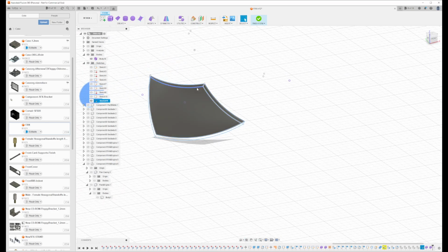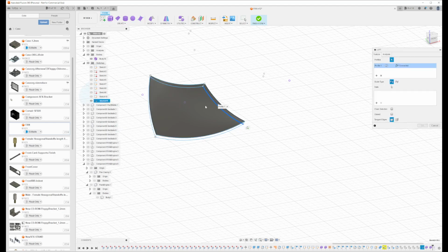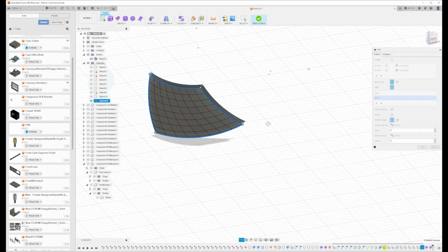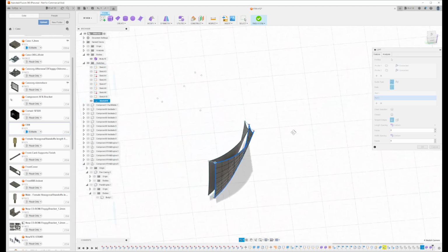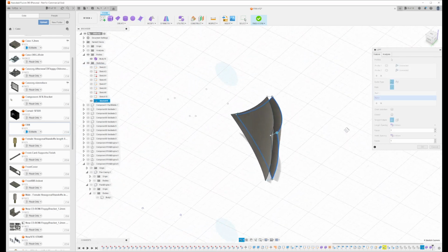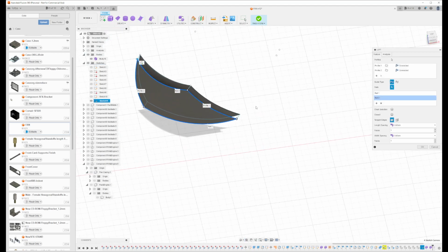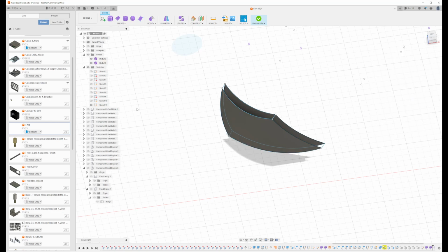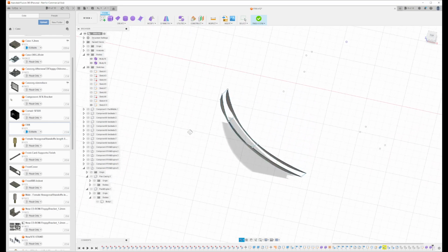So you rotate around, you do the same, you go to create, loft, and I select this side and this, and again I click on rail and this. See? You're starting to see the point now. And then 1 and 1. So now you have 2 sides. And you need to have solid lines, you cannot use dotted lines for this. Press OK. Still have the sketch up, so we'll just use more lofts.